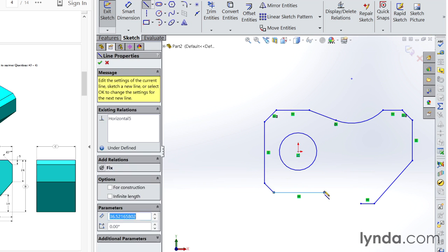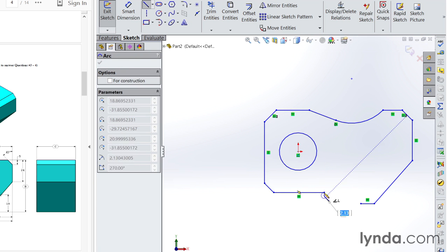goes across. Now we've got an arc we need to create, so it's going to be a tangent arc. So I'm going to go back on here and come back out as a tangent arc. Make sure I'm coming out the right direction, which I'm not. You see, there's where we want it. And then one more tangent arc off of that, so it's going to be a tangent arc here. And let's just end it down here.